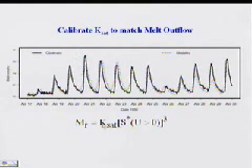And you can see that this lumped approach we've taken, where we don't worry about the penetration of a surface wetting front, but we just say there's a bulk amount of water in the snowpack and the drainage rate is proportional to that, seems to work reasonably well. It does say that the melt starts a little bit in advance of where the observations recorded, because presumably that time lag is the time it takes for meltwater that's primarily generated at the surface to reach the melt collector. So it's not a perfect representation of the melt process, but it's reasonably good.